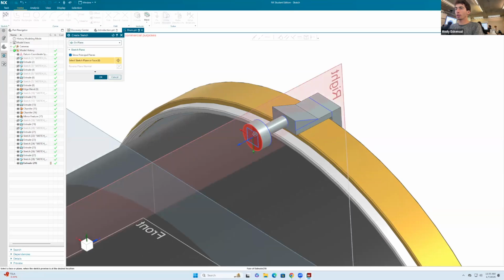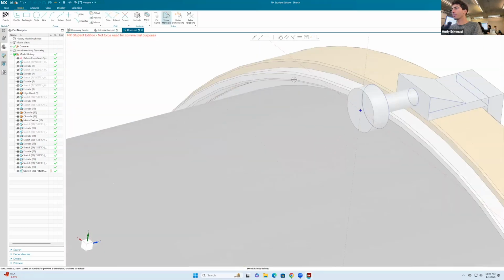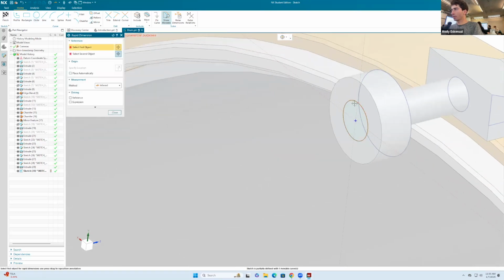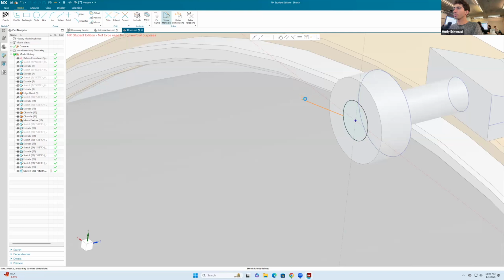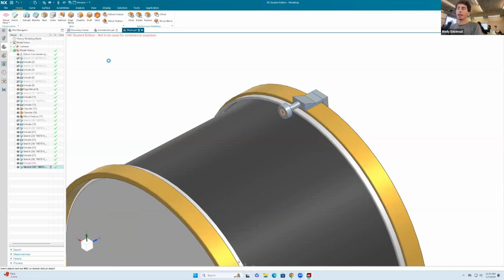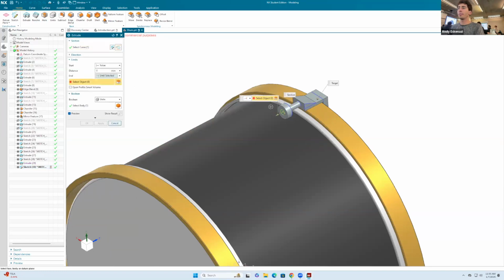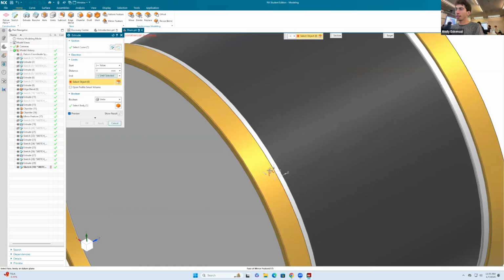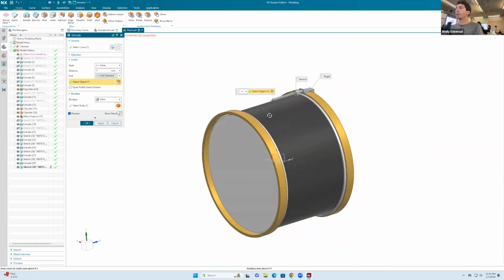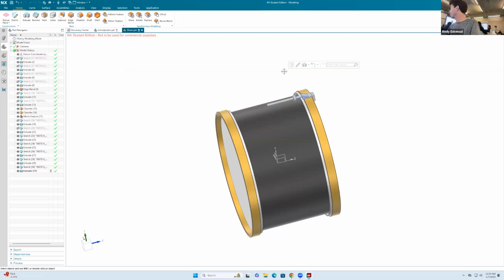And then I'll just continue that bar. So I'll go here to sketch in that face. Letter D, that too, okay. And just like that, I'll extrude, and instead I'll use until selected. And for until selected, I can select again that plane, which is the middle plane. So we'll go right until the middle. That way we can mirror all of this stuff afterwards.